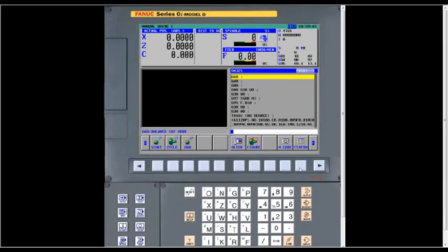You can use a G code to do it, or in your settings, you can go in and change it there. But now, just a further answer to that question, there are some things that you have to set up where you have to be in metric mode. Like in probing, when you go in and actually set up the probe, it'll tell you in there that everything has to be done in metric.